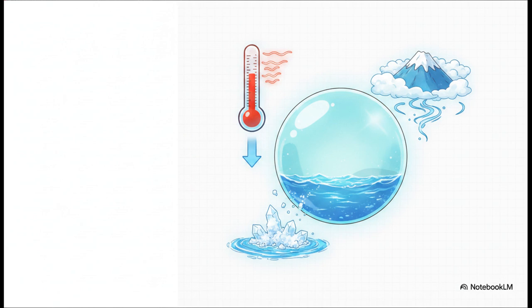As water temperature rises, its ability to hold oxygen drops. When atmospheric pressure drops, say you're up at a really high altitude, DO levels also decrease. And finally, salinity plays a huge role. Saltier ocean water holds way less oxygen than fresh river water. Combined, these three factors define the absolute maximum amount of oxygen your specific water system can hold.